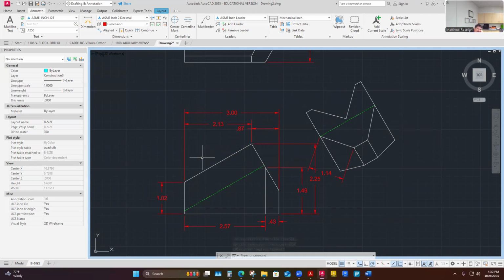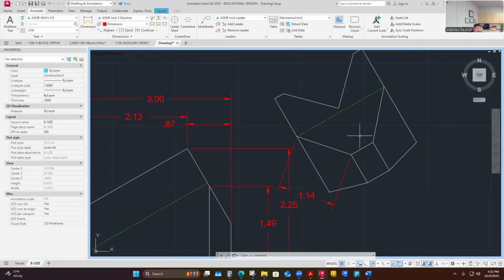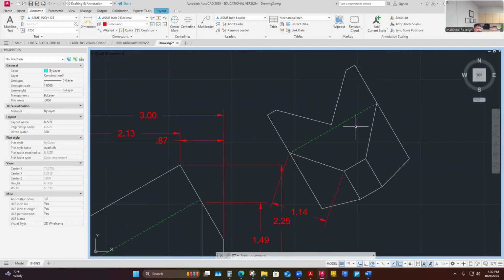Sometimes align dimensions become reference dimensions. Sometimes ASME says don't do it. So I'm going to do kind of a hack method of dimensioning over here for us to know why we established that was for the true length that it holds. And that's one of the true lengths that it holds, 1.14, and it's there and it's there. And so I can choose to dimension probably either side.